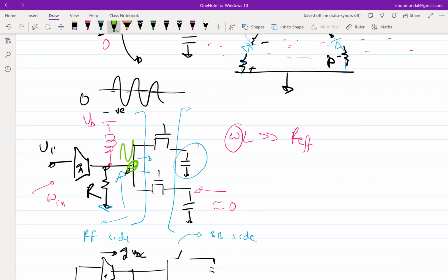So the LNA that you are designing for the assignment, I assume you are using the one that has been covered in the class. Then you have a common source, then you have a cascode. On top of that, you probably have an LC tank. The LC tank can go above VDD. The voltage on the top of the cascode can go above VDD. That's not a problem, right? But if you directly use that operating point to bias the mixer, then this mixer is going to have a problem because this guy will be at a much higher voltage, maybe around VDD, quiescent wise.